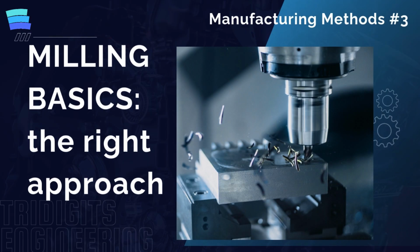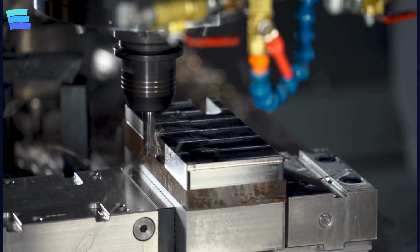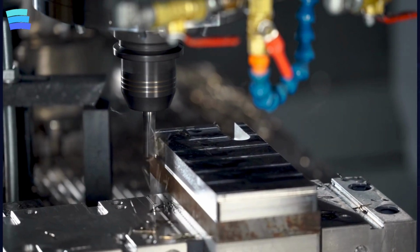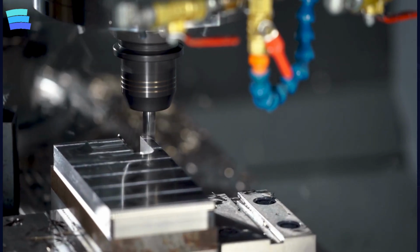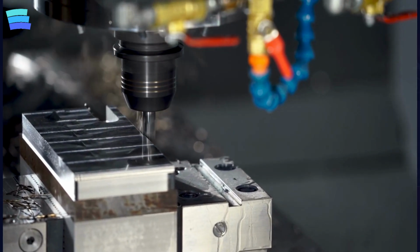Today we will look at milling not by asking can it be milled, but by asking when it is the right choice and when it creates unnecessary operational overhead. Milling follows a simple principle. A rotating cutter removes material from the workpiece while the part or the tool moves in controlled X, Y, and Z axis. This method is extremely strong for prismatic geometry rather than rotational geometry, flat faces, pockets, channels, shoulders, profiles,